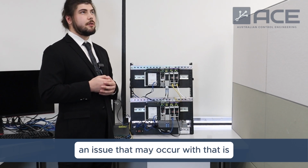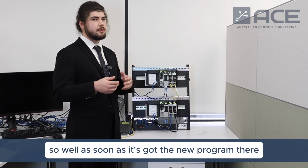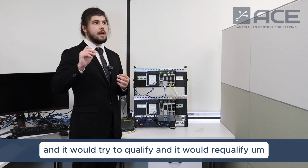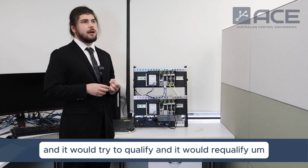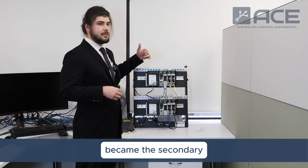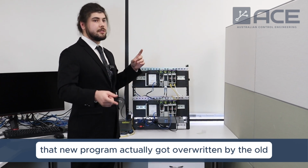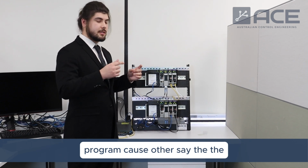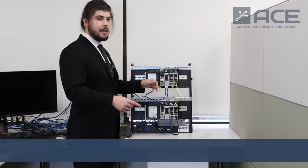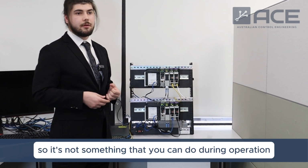An issue that may occur with that is if you had auto synchronization on, so as soon as it's got the new program there, it would try to qualify, and then it would re-qualify. What you'd have is that the PLC that you uploaded the program to became the secondary, and now you're resynchronizing it with the primary. That new program would actually get overwritten by the old program, because as I say, the program that's in the primary is cross-loaded to the secondary, and if the new program was on the secondary, you just lost that program. So it's not something that you can do during operation.